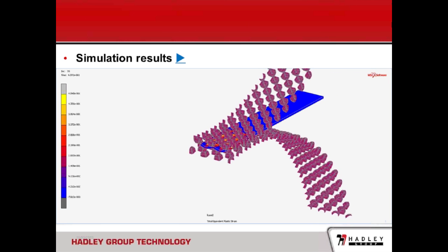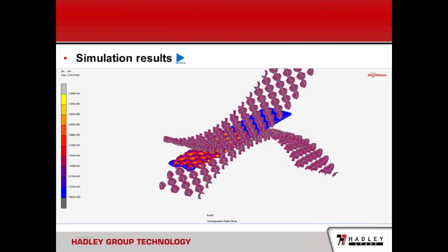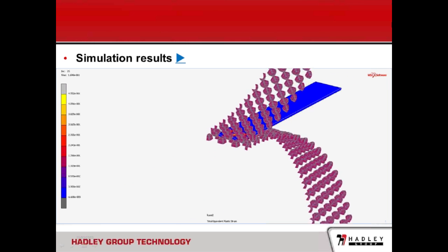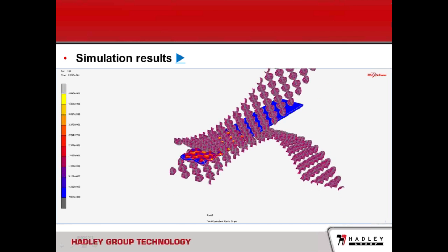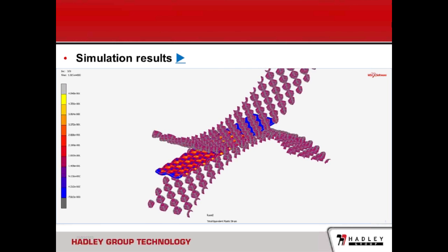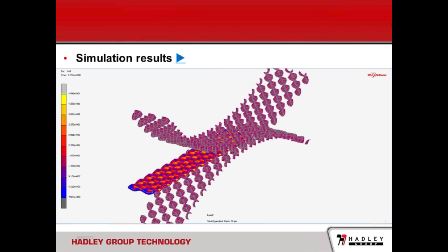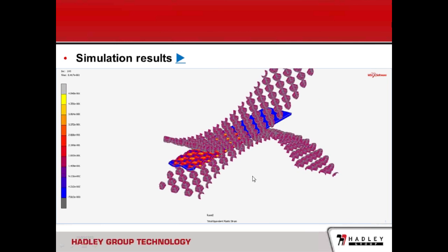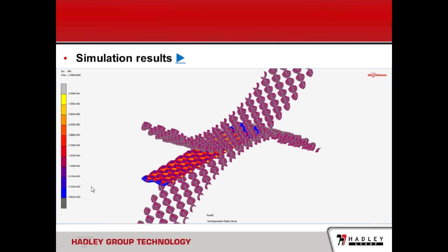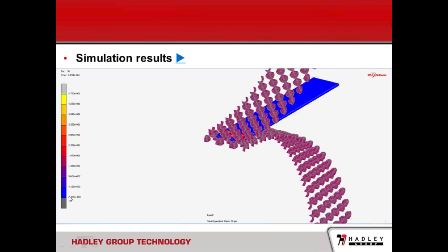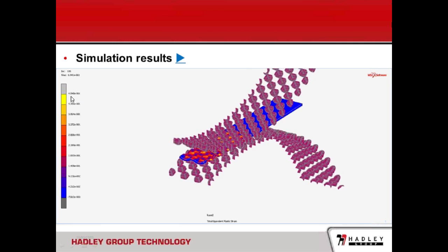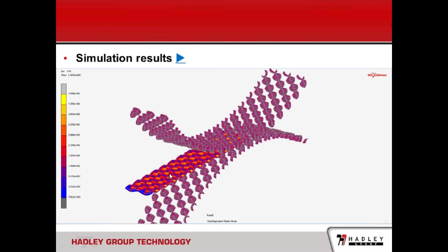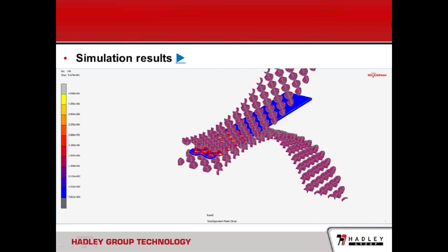And here I show you the animation of the simulation, and you can see in the animation that the flush strip is stressed, and the dimple is applied on the strip during the process. The color represents the plastic strain developed in the strip during the process, with the magnitude from minimum, associated with the color blue, to the maximum, associated with yellow. So you can see the plastic strain developed in the strip during the process.